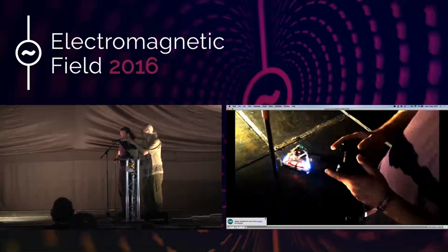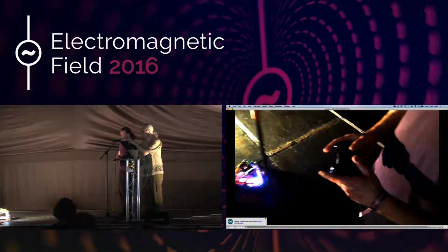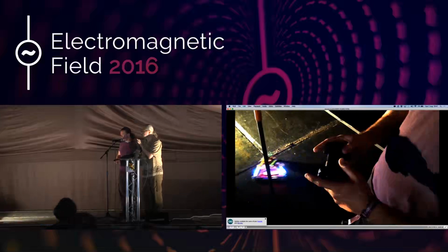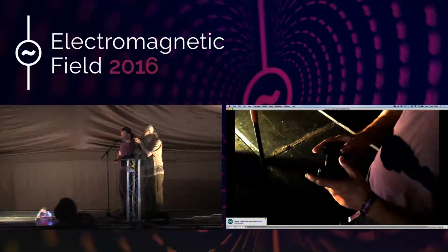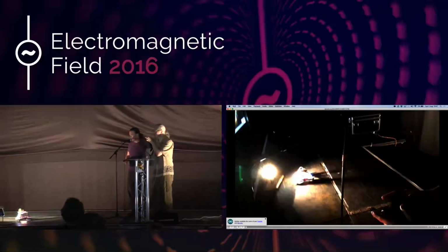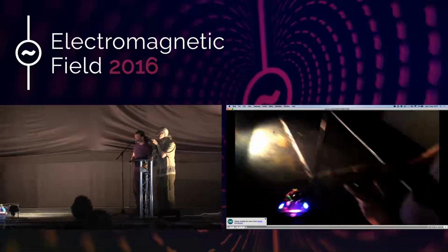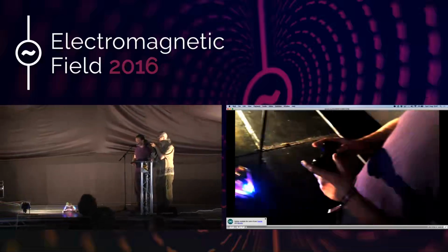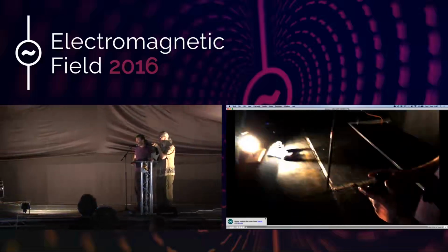So what's happening is that the code is doing dead reckoning, and it allows me to have a motion where I turn and translate at the same time. I'm just moving left on my joystick, and I'm spinning the robot. And it's not 100% accurate because it's skidding slightly. You can hear the wheel that got damaged earlier.